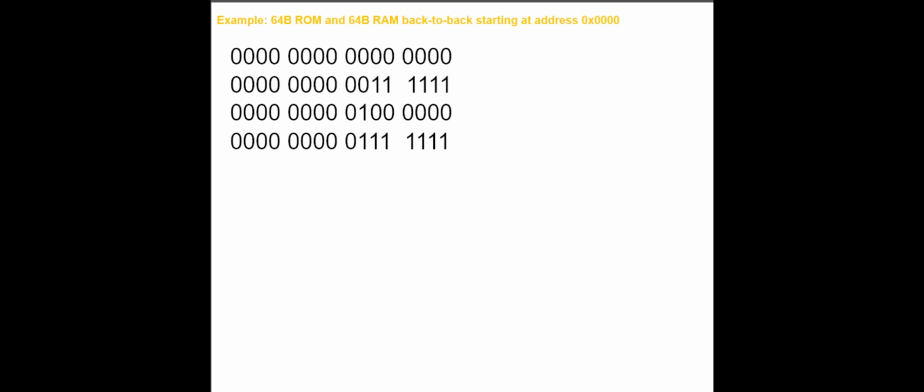Okay, so now let's build on what we covered previously to figure out how to do the memory address decoding, given that we know the address range for different types of memory. So I'm going to use the same example that we did in the previous video and use this information to help me navigate my address decoding. We said the first range was for the ROM, and then the next one was for the RAM. And I want to figure out which bits I care about in order to select between the RAM and the ROM in this memory system.